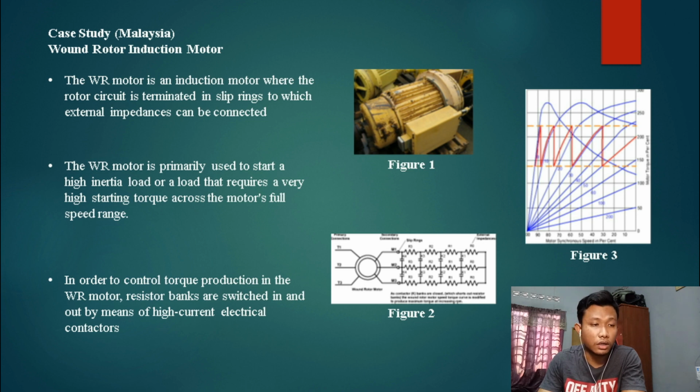That is the list of potential issues. Lastly, newer active front end VFD systems can regulate power factor close to unity, and regenerated energy can be used by other drives connected to the common power distribution network, thus providing energy savings, power factor improvement and better speed control.